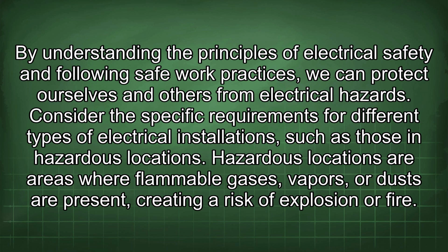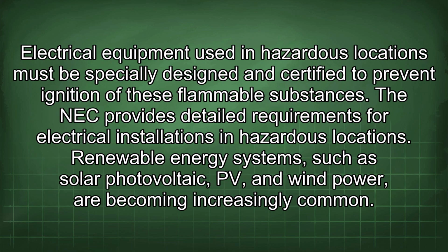Consider the specific requirements for different types of electrical installations, such as those in hazardous locations. Hazardous locations are areas where flammable gases, vapors, or dust are present, creating a risk of explosion or fire. Electrical equipment used in hazardous locations must be specially designed and certified to prevent ignition of these flammable substances. The NEC provides detailed requirements for electrical installations in hazardous locations.